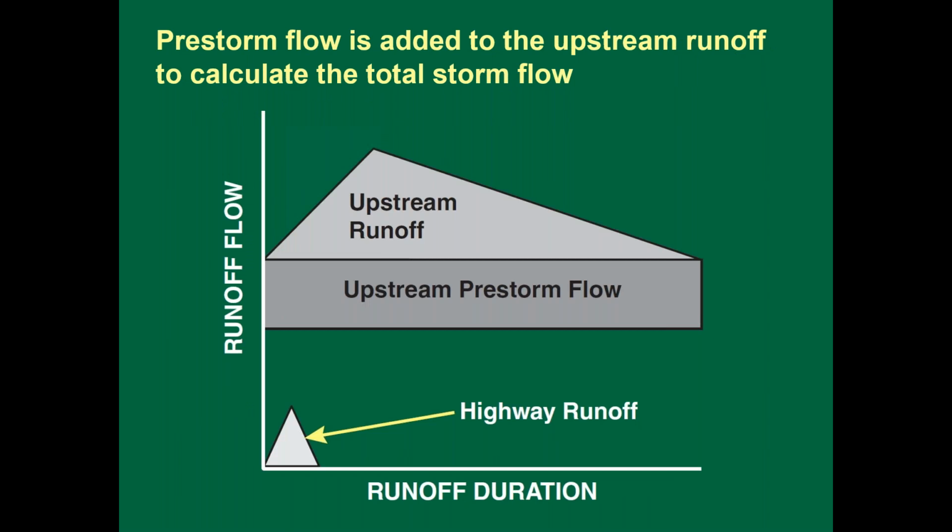So what we look at is, in the hydrology of the system, pre-storm flow and then upstream runoff. As this diagram indicates, the pre-storm flow times the runoff duration is added to the upstream runoff to calculate the upstream total flow used for dilution calculations.